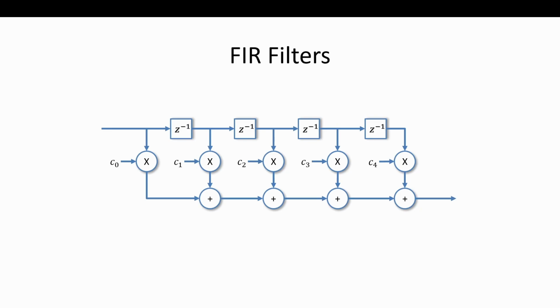It's a subset of all digital filters that we could do. There's also IIR, Infinite Impulse Response, and then even within FIR, we're doing the subset that is linear phase FIR filters. We'll talk a little bit about what that means, but linear phase FIR filters are what we're going to talk about today, and that will carry you through a lot of the filters you need to design. If you want to get good at digital filters, this is a great starting point, and it's also what I can tell you about in 2 hours.